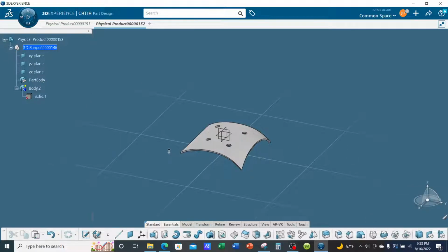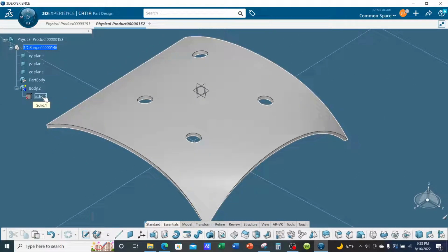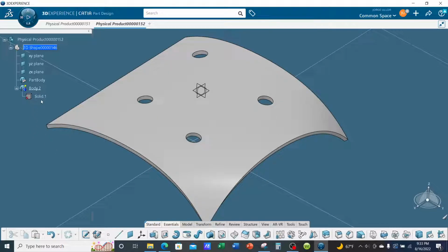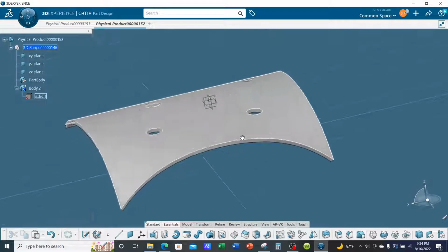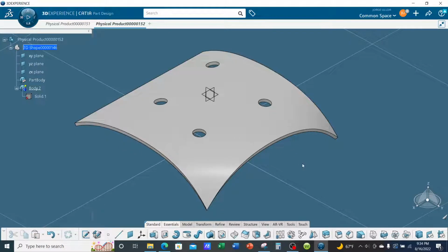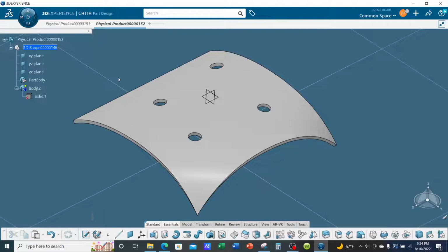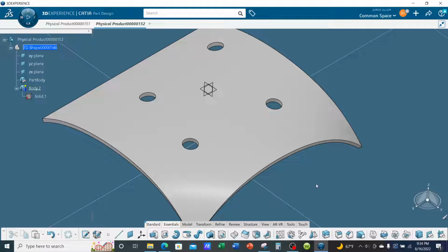So it's quite common in manufacturing to once again not have the smart model with all the history. Probably it was done in a different software, or maybe you're using a different software other than Catia to do design work, for tooling, for molds, or for tooling, like a form block. Alright, so notice there's no holes in the history. So one thing you can do is you can fill the holes by adding material.